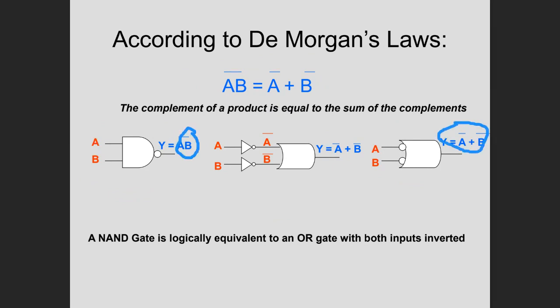Well, the trick is that if I use the term "demorganize," I give you an expression and I say demorganize it, that means something's knotted, because this only works with either the NOR or the NAND. So you're going to have this bar, that not symbol. And what you do to demorganize it in algebra, you just take this line and you break it, and then you change the sign. Now this sign here is a dot. So if you remember this: break the line, change the sign. Break the line, change the sign. That's what I mean by De Morgan.